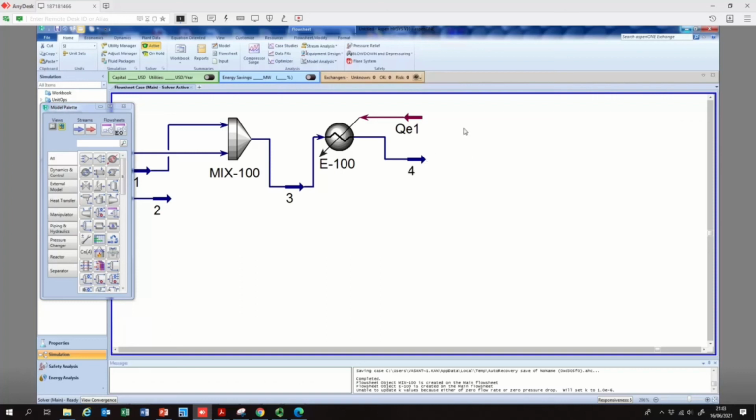So we cannot add a reactor and then define, okay, this reactor is maintained at 800 degrees centigrade. No, you can't mention that. So all we need to do is add a CSTR and just make sure that your fluid stream enters at the right conditions, like the right temperature and pressure that should be maintained inside the main unit, which is the mixing tank.